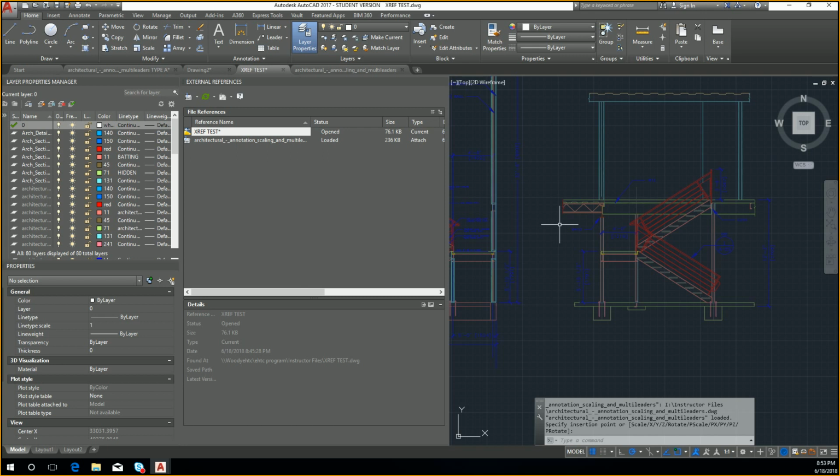So if you go close right now, select both of the blocks in there. Okay, and then type explode. Explode again. Okay. Now go and type PU. Now open up the blocks list. You should be able to see it now on the bottom. There you go. Because that's how AutoCAD protects you from breaking your own stuff. It doesn't want you to purge anything that's living, right?